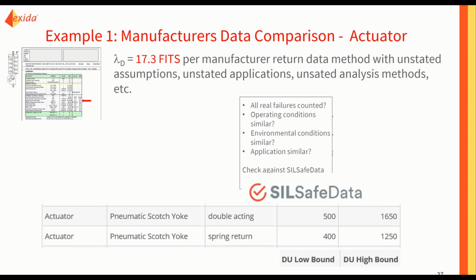Let's look at SIL-safe data. That's a Scotch yoke actuator. It's not double acting, it is spring return. So the number should be between 400 FITs and 1250.